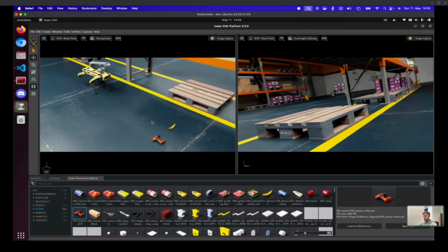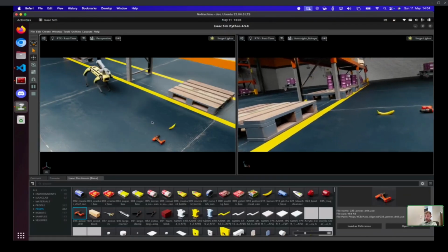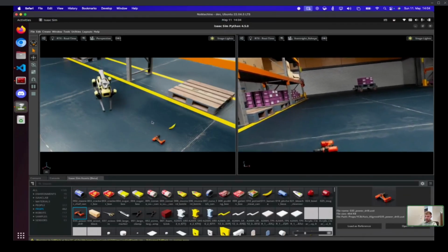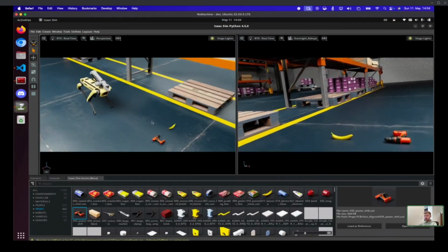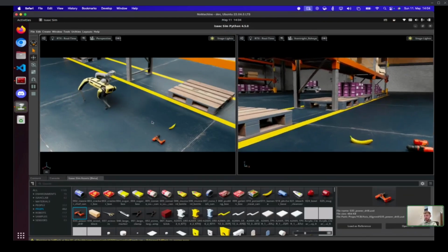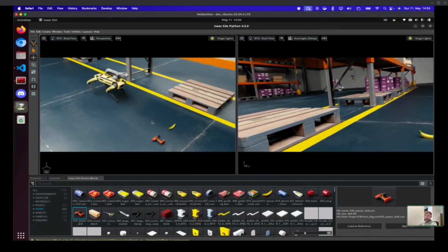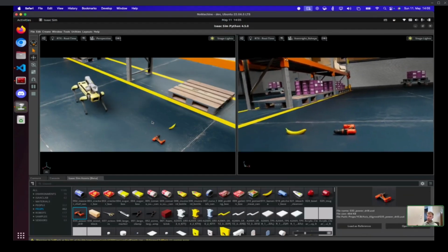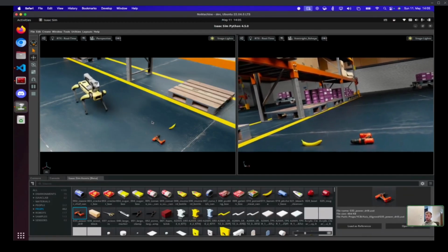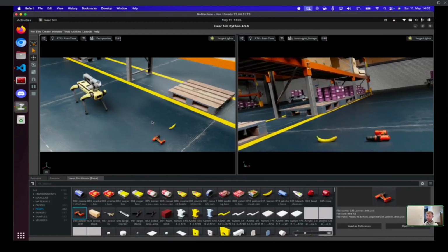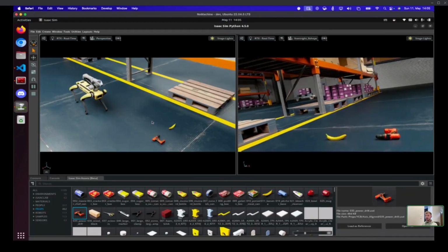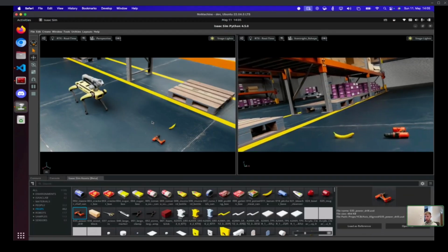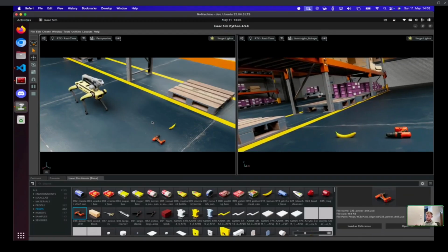Maybe what I can show here is when the robot is moving around. So I'm moving it around with my keyboard at the moment. You can see the arm is doing some jerky movements here. The reason for this is I didn't yet properly define the reward function to penalize unnecessary arm movements. So one solution could be defining a stow position of the arm, and in every step the arm is moved unnecessarily, it's going to be penalized.